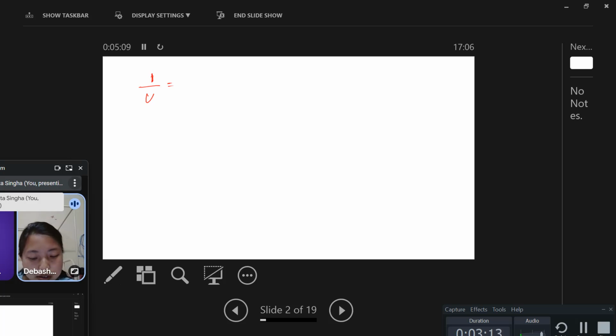So this is the total resistance, suppose 1 by UiAi. It can also be written as 1 by U naught A naught. That means this is based on the inside tube, and this is based on the outside tube. So this is equal, and this can be given by 1 by hiAi plus R wall.